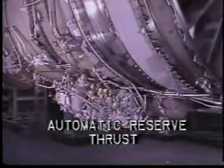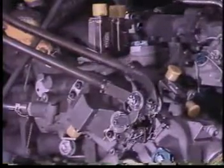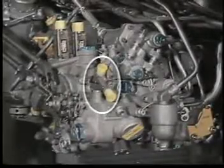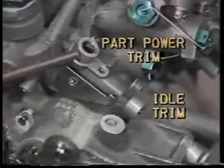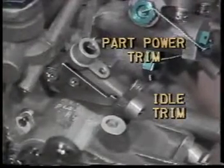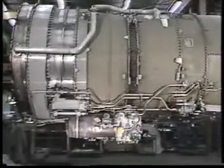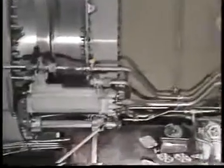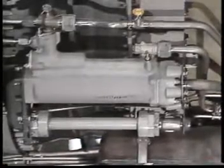If necessary, this higher thrust setting can be achieved manually by advancing the throttle. There are only 2 line maintenance adjustments on the fuel control: idle trim and part power trim. These adjustments must be made periodically to maintain optimum engine operation. The fuel flow transmitter, which is normally located here, measures the fuel flow and sends this information to the fuel flow indicator on the flight deck.